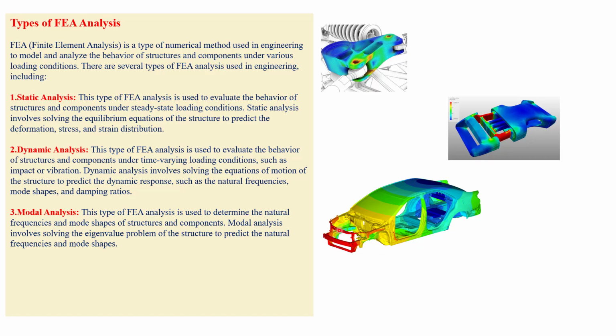The first 6 will be 0, as you all know, and then the 7th should be torsion, front torsion and back torsion, and then the bending will happen: front bending, rear bending, even the middle bending, depending. So after the 6th mode, this behavior is expected, very important.